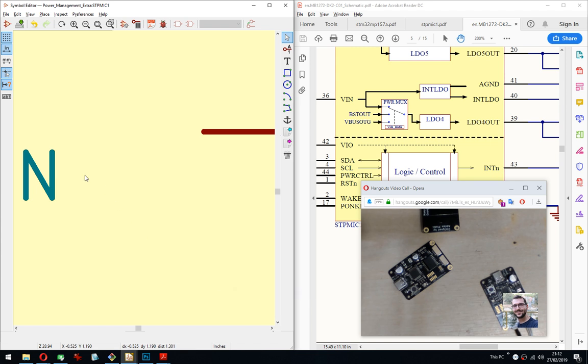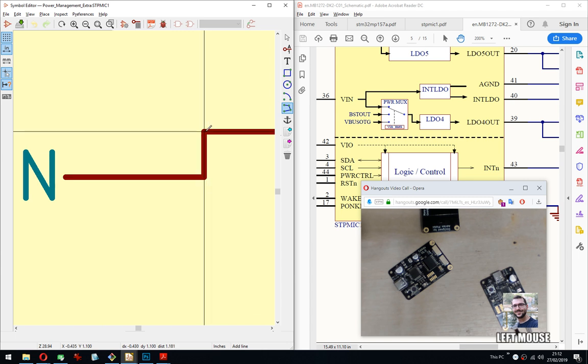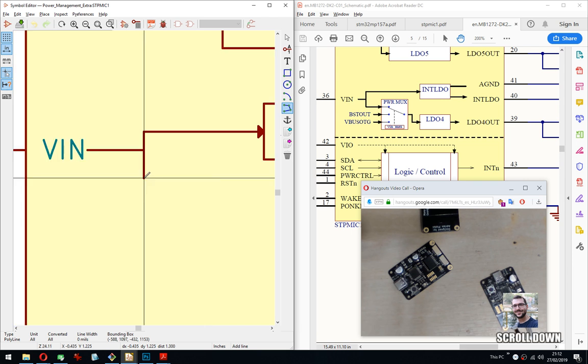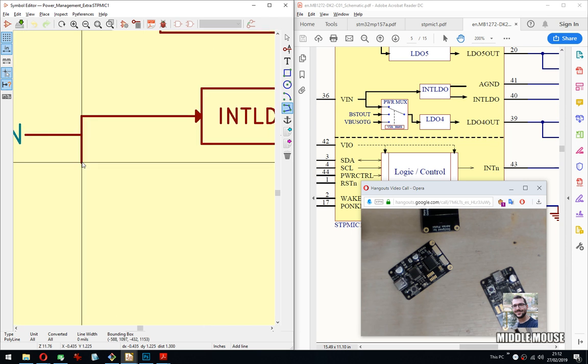I can just ship 2 JST-GH cables and a termination thing breakout with power connectors and a converter, and just a breakout board. I think that's probably the most versatile, because it allows you to have the termination at one end and also inject power to the system, right?